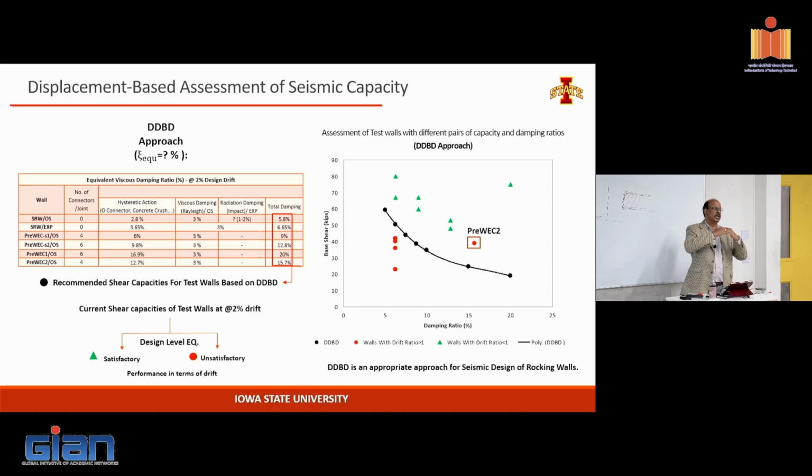So there are no other places where the wall will open up. There are one or two research efforts that actually looked at opening it up at a couple of different places rather than one location. I really don't see a benefit. Now your other question is, how would they rock? Well, if they're rigid walls, unless you restrain the rocking, they should rock because they're rigid and they're not held anywhere. So the only problem that interferes is if you connect the floor to the wall, for example. I think that's what you are also asking, right?